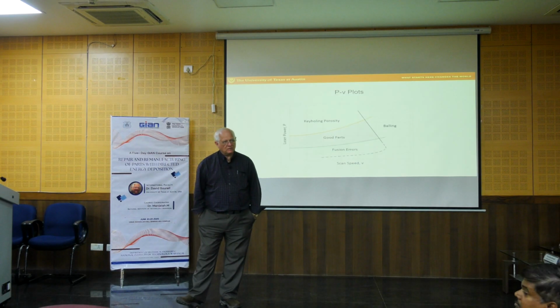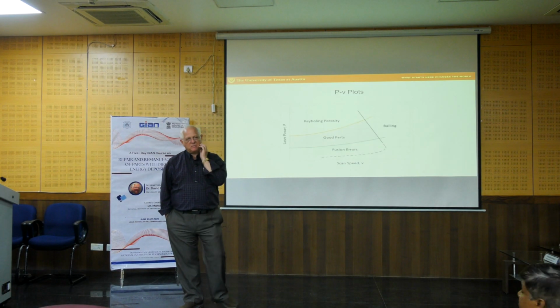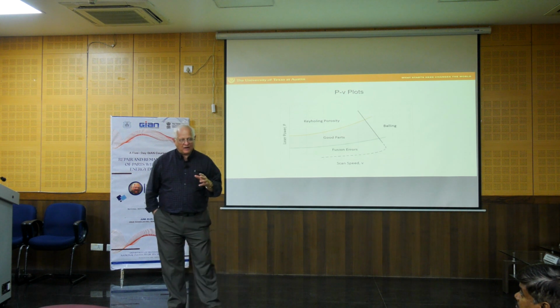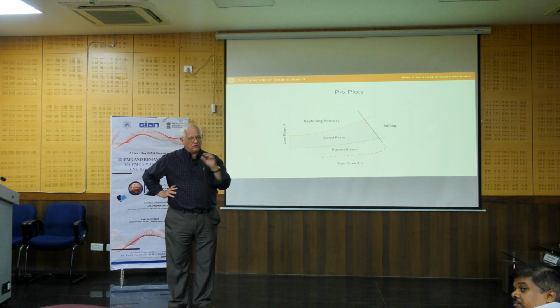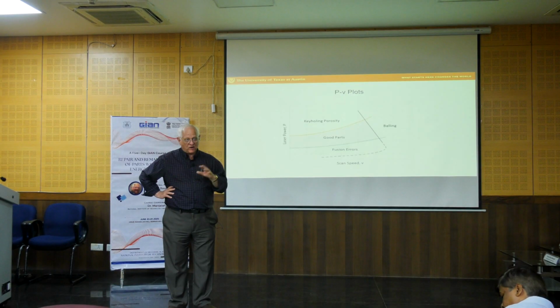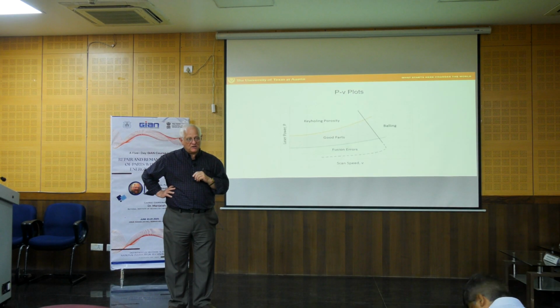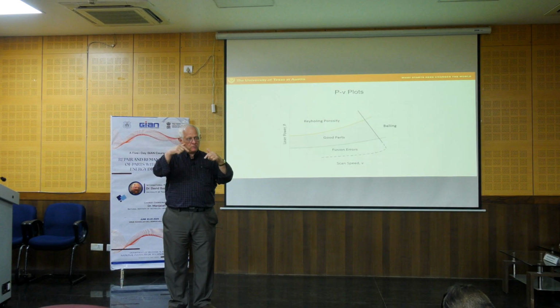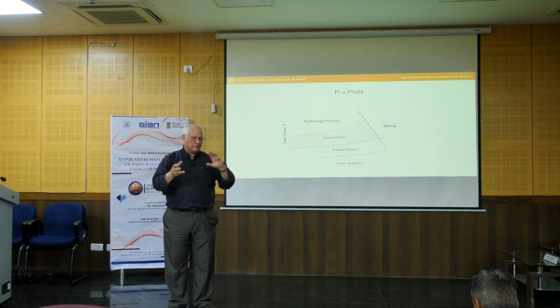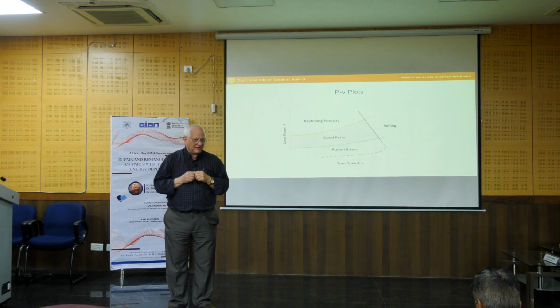Right. Sure. Functionally graded materials is a very interesting area, and it turns out that of all of the processes for additive manufacturing, direct energy deposition is the one that I think is best suited for producing multiple materials. We can simply have multiple powder jets of different materials, and you just turn them on and turn them off depending on where the scan is, and you can create these parts.